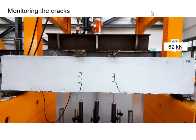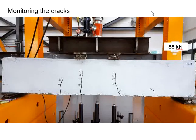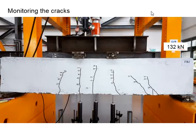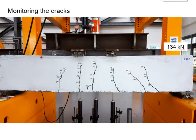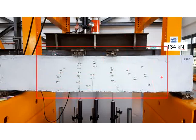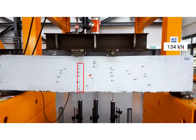Now, if you combine the photos together, you will see the propagation of the cracks until the failure of the specimen. Personally, I do not recommend tracing the crack lines, as the crack width sometimes also gives you significant information. It reflects the severity of the crack, indicating the failure modes.